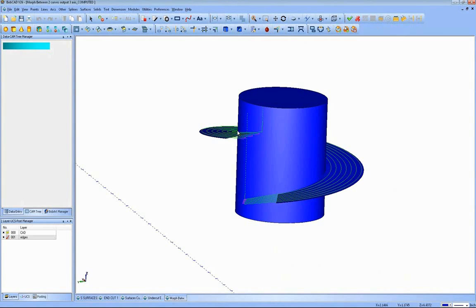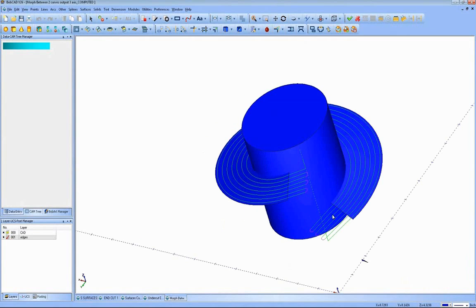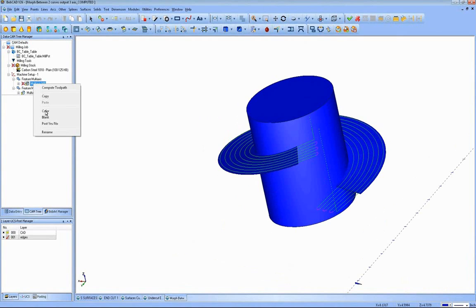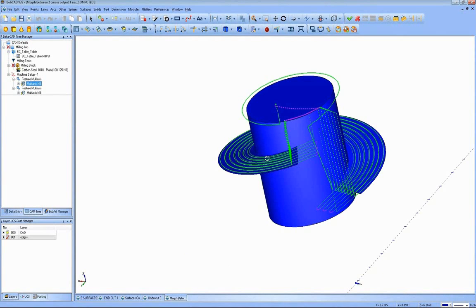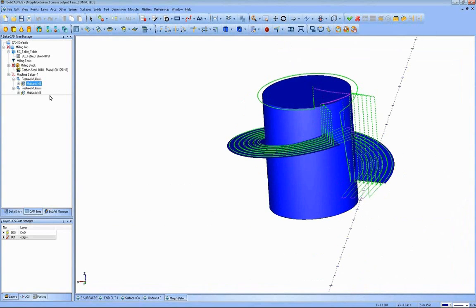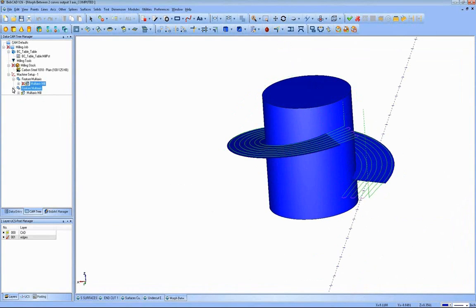This one, we can actually tool path right off the part, and we can get the tool path to be compensated for whatever flat bottom or ball tool that we're using. Very easy to do, and you can see how I was able to extend those over as well to make sure that they come cleaned in. Again, to do a tool path cut like this, as you can see, we have a couple different ones here. Actually, if I unblank this, you can see I did another one in there around the top, kind of like a step down as well. We'll just leave that blanked out for now. And this is the one that I wanted to look at here.